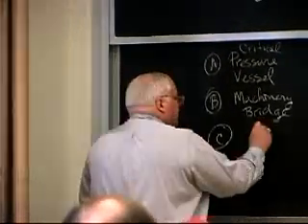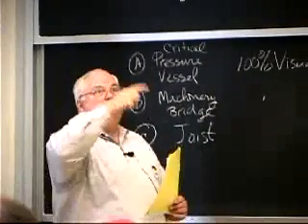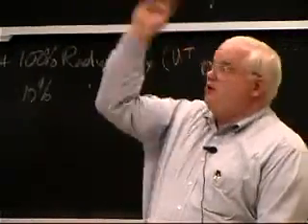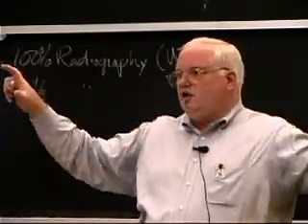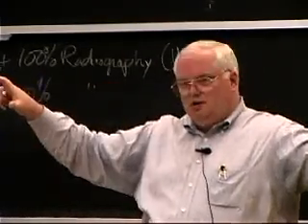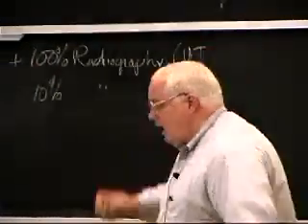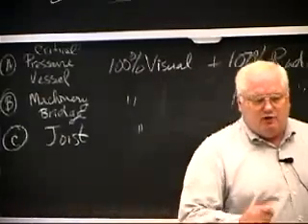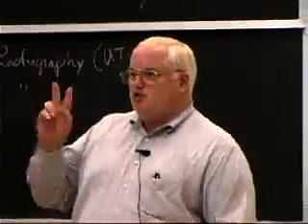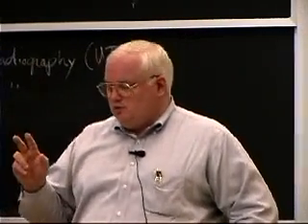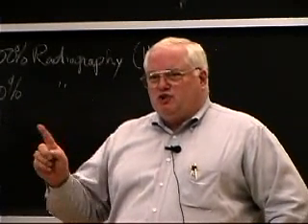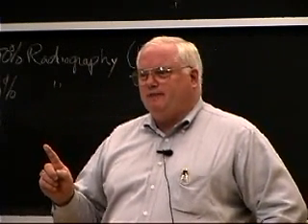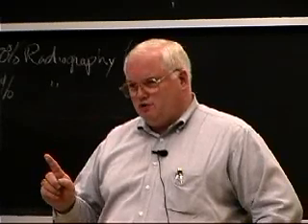What about a joist? Okay, a joist being, well, not in here, this is a concrete building, but if you go to a shopping mall and you were to peel away the false ceiling, you would see these steel bar joists up there. Basically they are the beams that are holding up the roof. I will tell you that inspection is 100% visual and nothing else on those welds. I also tell you that the average welder has 2 seconds to make those welds per weld, and he's supposed to do the visual inspection himself. Okay? How good a visual inspection do you think that is?